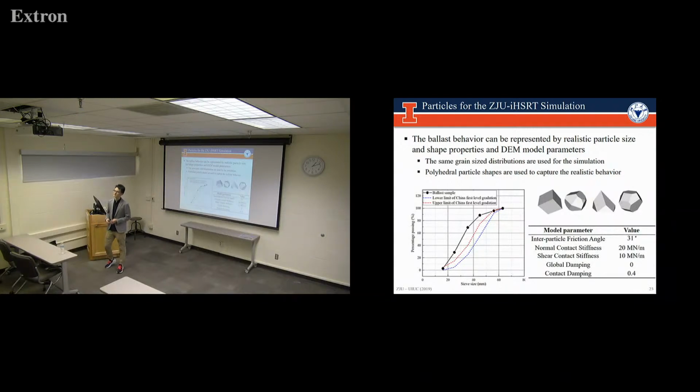Well, but quite a bit changes according to the condition of the loading. Right. And special track locations that actually get pounded more with loading, the ballast life is actually much shorter. Maintenance cycles are much more frequent. Things like those. So understanding that from the field and bringing it into realistic modeling is needed. There's a lot going on at the maintenance end of how deterioration is actually happening in the field.